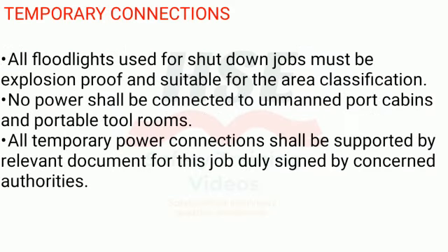All floodlights used for shutdown jobs must be explosion-proof and suitable for the area classification. No power shall be connected to unmanned port cabins and portable tool rooms. All temporary power connections shall be supported by relevant document for this job duly signed by concerned authorities.